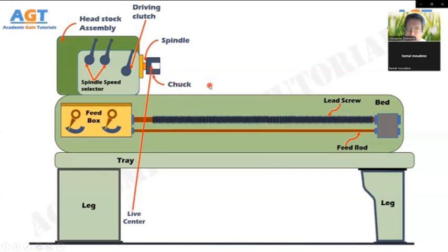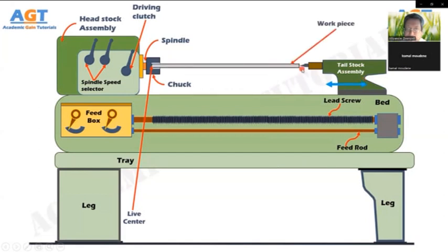The tailstock is situated on the right side above the lathe bed. It is made out of cast iron. The tailstock moves on the guideways on the bed surface, and it can be moved forward and backward, towards and away from the chuck according to requirement and job length. The tailstock is used for supporting the long end of the job for holding and minimizes its vibration and sagging, so that the long workpiece or long job does not deflect or bend during the machining operation.